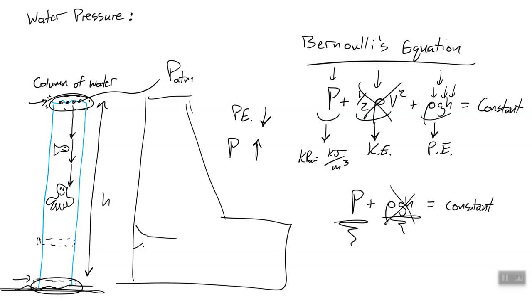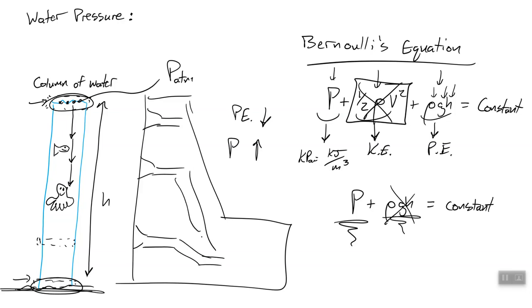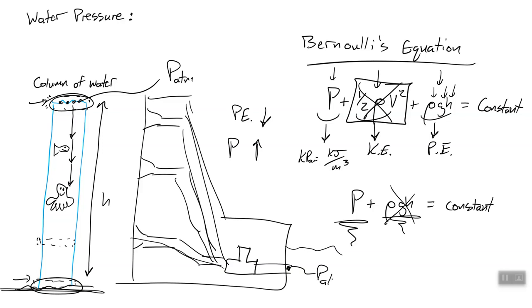So no matter where we put this part of the dam that's going to take out the water, it doesn't matter, because eventually all of it will be turned into kinetic energy, because there will be some slight decrease here, more of a decrease there, more of a decrease there. So we're always going to drop to the same height to get to the turbine, and then we're always decreasing the pressure as we move along, because our outtake is exposed to water almost at atmospheric pressure. So say the outtake is about at atmospheric pressure. So no matter what, we're going to get some pressure and some velocity entering here, and it will be about the same no matter where we take out the water.